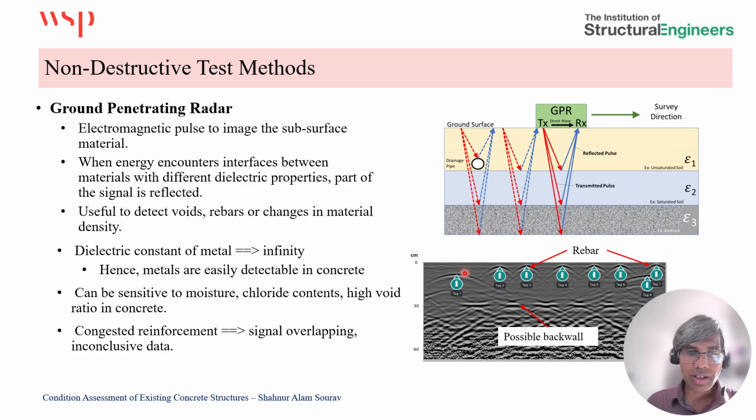So when it comes to the reinforcement within the concrete, the ratio of these two dielectric properties of the material is infinity. So in that case, most of the GPR signal will be reflected back at the surface of the reinforcement. So within concrete, we should be able to easily detect the reinforcement, depending on the depth of the reinforcement and also the quality of the reinforcement.